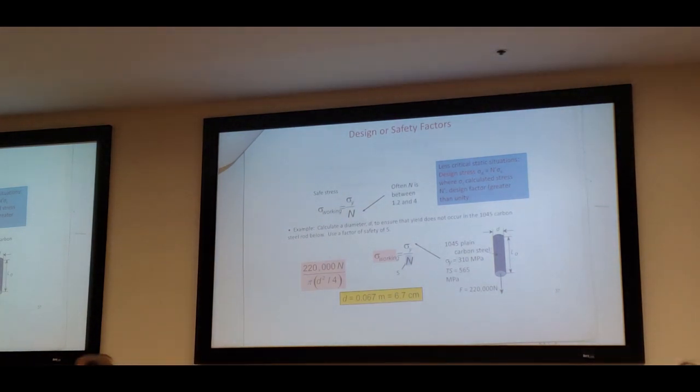So that's the reason why you need to be very careful when you design something. As engineers, you should be really aware of these type of things. When you design a structure with the materials, there can always be defects in the system. And the 20th century approach was to use a sample with a strength much higher than that required. Okay, higher than that required. That was the strategy. Did you get it?